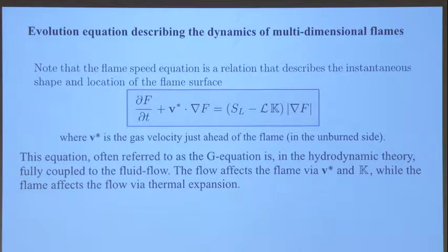This equation cannot by itself tell you everything about the flame, because you need to know the flow velocity, and the flow velocity is affected by gas expansion, and so you really have to solve this coupled with your Navier-Stokes equation.